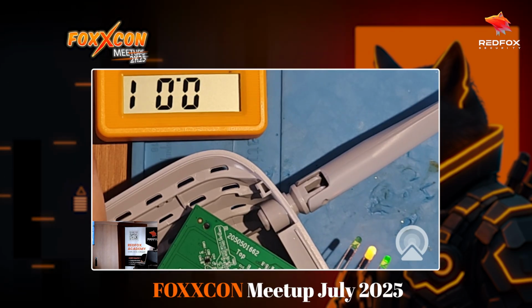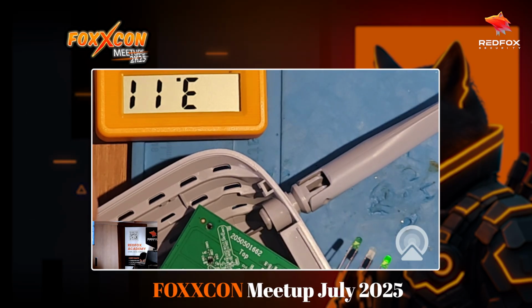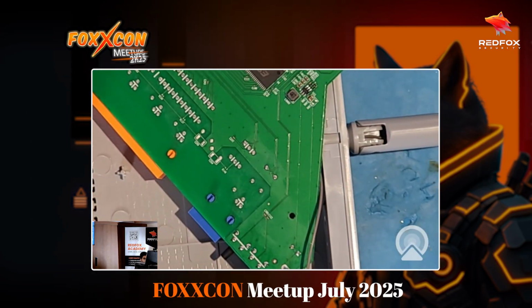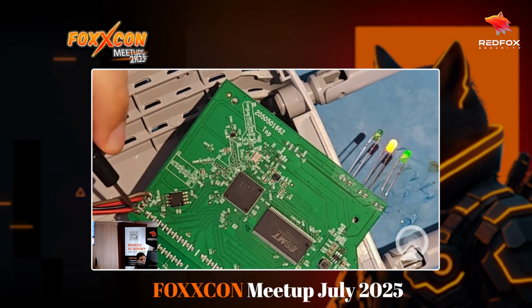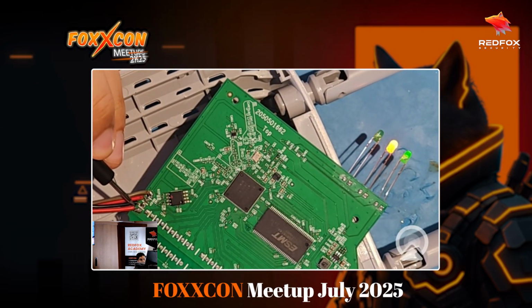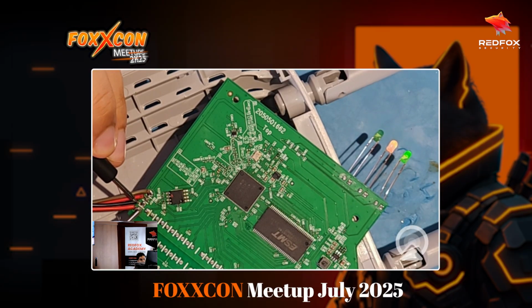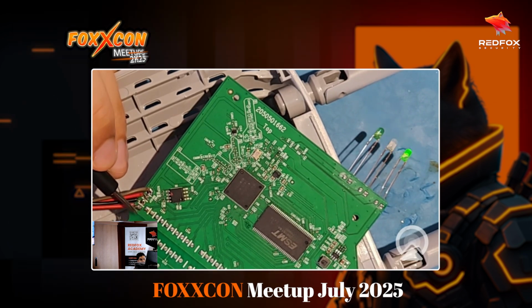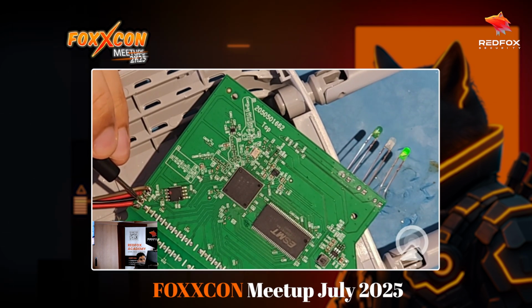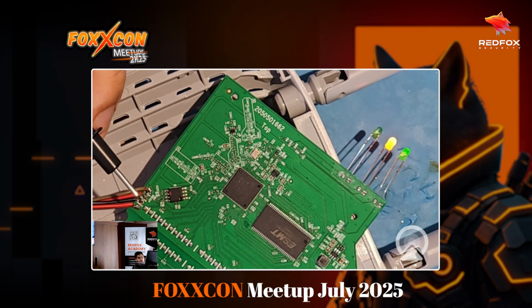All right, so this is the one that we're looking for, which is the first one. I'll show that quickly. You see, this is the ground one, the black wire, and this is the one that I was testing first, the red one right here. So this is your power, the middle one, the second one from the start is your ground, and now we need to figure out which one is your data receive and data out, which is transmit.